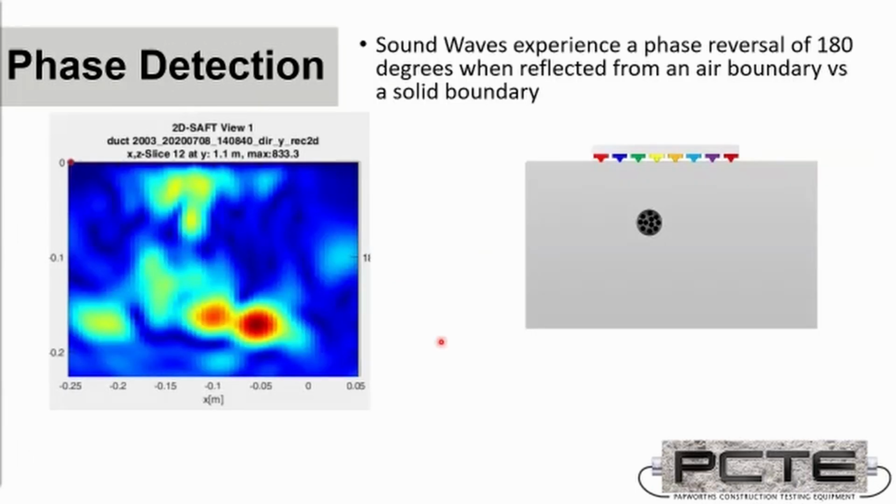And we did that using Proceq's Pundit PD8000 array, where we collected measurements over the ducts. So we'd get, as a typical reflection, a reflection from the duct and a secondary reflection from the thickness of the slab with a bit of shadowing underneath. One interpretation we could use is to look at the strength of this reflection, but the particular post-processing we did with Pundit Vision software, which used to be known as Intersaft, was to process